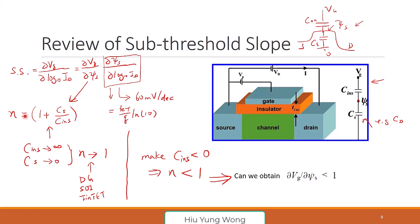So this is even better than using the fully depleted SOI. Yes, because fully depleted SOI only gives you, if you do it very well, 60 millivolt per decade. This one, I can go below 60 millivolt per decade. If you're interested, after this class, just Google "sub 60 millivolt per decade." It pops up tons of papers talking about how they get sub 60 millivolt per decade. And if you also type "negative capacitance," then it will be all about the experiment and simulation for this sub 60 millivolt per decade using ferroelectric devices.